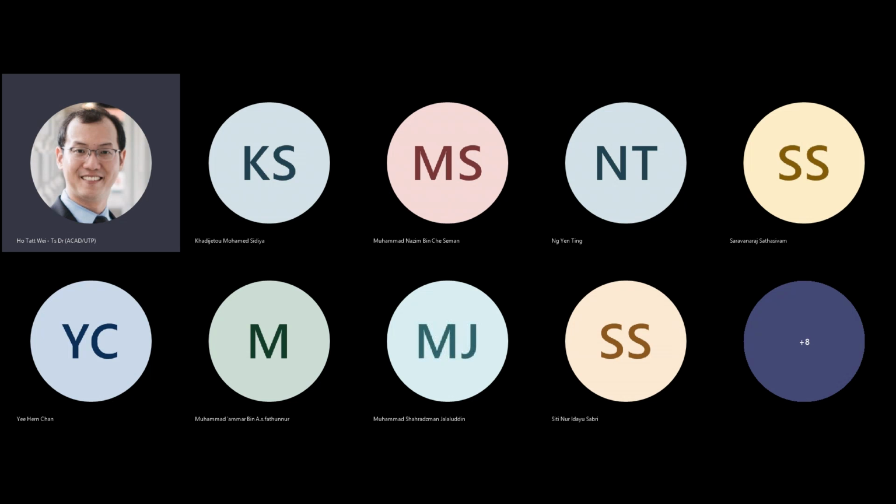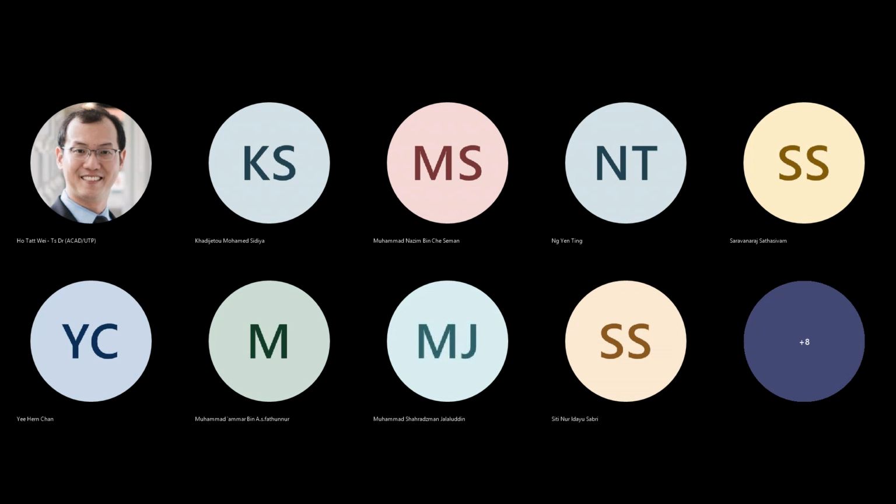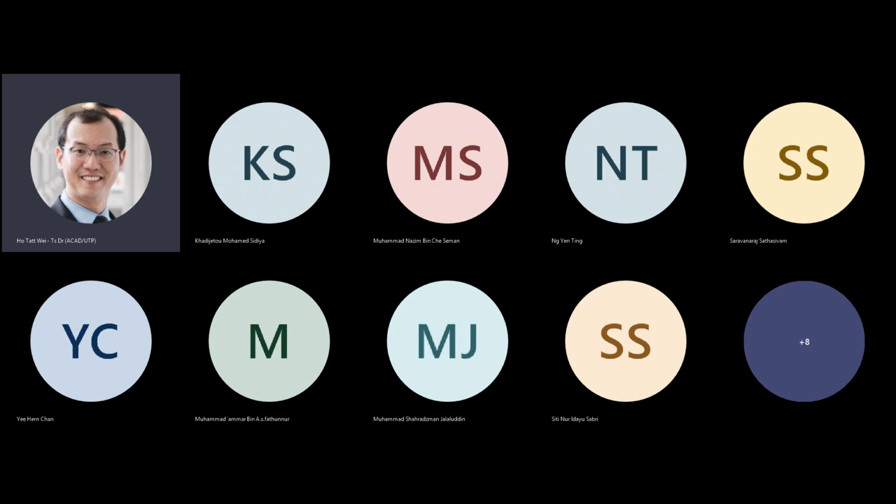Remember that we said a MOSFET is equivalent to a switch. So if I put a logic level here and I set this to be the control pin, if the gate here is a logic 1, the channel is formed here, so this is conducting at the output, and if I set it to logic 0, this channel is not conducting.